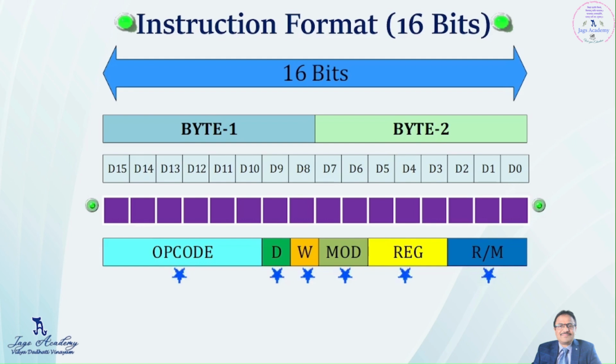All of you know that you're writing the program using assembly instructions. All of you have done this in your class, in your lab. Suppose I say move AL comma BL, or the same instruction which I just used now, move AL comma within the square bracket 1 2 3 4. Right? Okay. See, whenever a square bracket comes in your instruction, that means something like a memory read or memory write is happening there. Inside the square bracket, you mention the address directly, or mention the address through the BX register, or through the BX and SI registers, through various addressing modes.